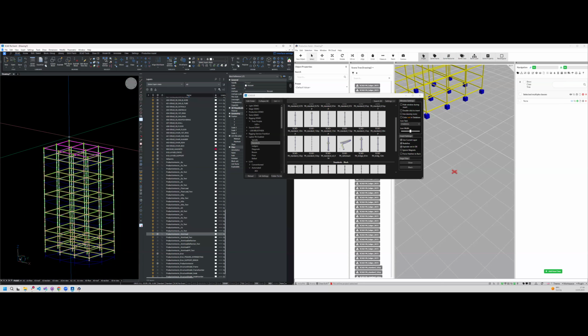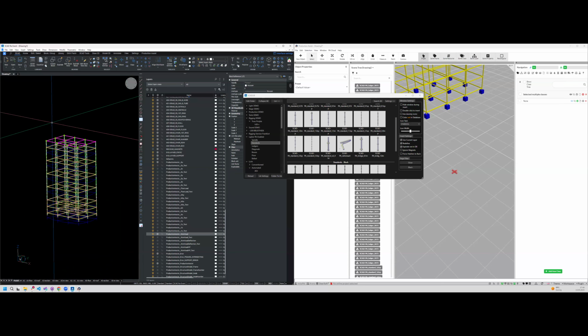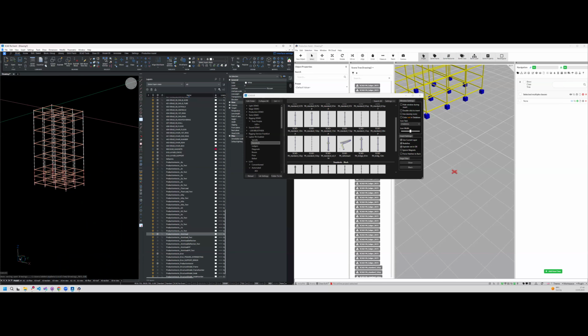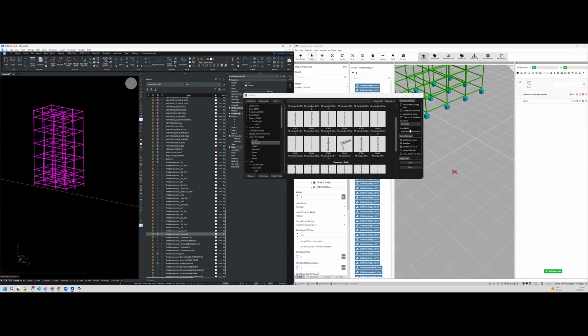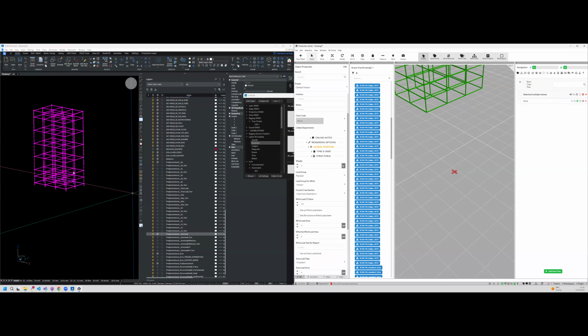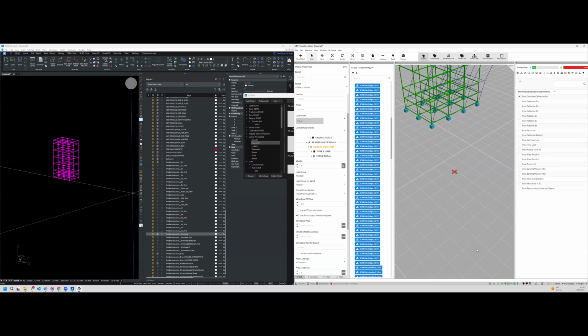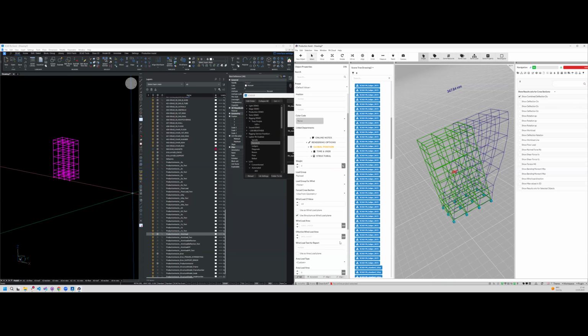So the first thing that we need to do in order to get to a reasonable level is selecting this and telling the structure that it should use this as a wind load plane. There's a button, use structure as a wind load, and then it will automatically calculate this. Wait, let me quickly also do the production system so that you see that it's shifting to the side like this.